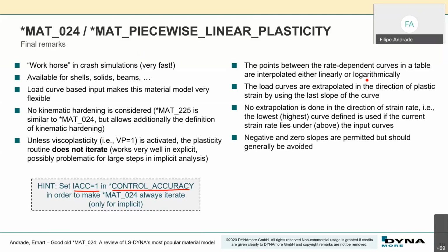The only thing I can say is that a well-resolved 3D surface for the plasticity will give you in general better results in your simulation. So the logarithmic option does that more easily than the linear. But if you use linear interpolation, you can also generate as many curves as you want, and you can also get the necessary resolution.